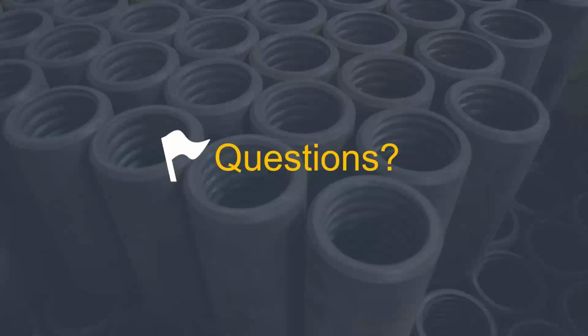Is that only a function of the soil? Most of the time you assume rigid, correct? Yeah, you want to assume rigid, and for small pile caps, it typically is. It's a function of soil and whatever material your foundation is made of, which is typically concrete. So it's a function of that particular site's soil conditions, as well as the material the foundation is made of. And you can improve that rigid condition through more reinforcement, through a thicker foundation, and there are other approaches to examining that fixed or rigid condition.